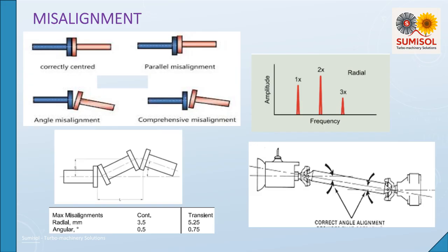DBSE plus margin. The margin must be maintained while positioning the coupling spacer. Refer GA as supplied by original equipment manufacturer. A high value of misalignment kills the intent of flexible coupling and causes severe cyclic stress. Cardan shaft, universal joints are also susceptible to misalignment. If there is very high vibration in connected component, some part of vibration may be transferred into adjacent component even